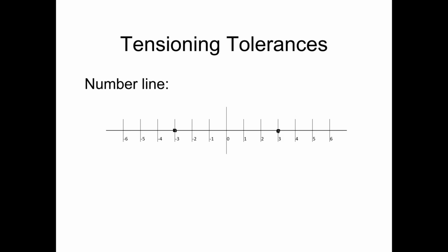All right, so let's determine whether or not this strand was tensioned within tolerance. First question, was the applied force within plus or minus 5% of the required force? Yes, we're at plus 3%, that's within plus or minus 5, so yes, the force was applied properly. Second question, is the measured elongation within plus or minus 5% of the calculated elongation? Yes, we're at minus 3%, that's within plus or minus 5% of the calculated elongation.